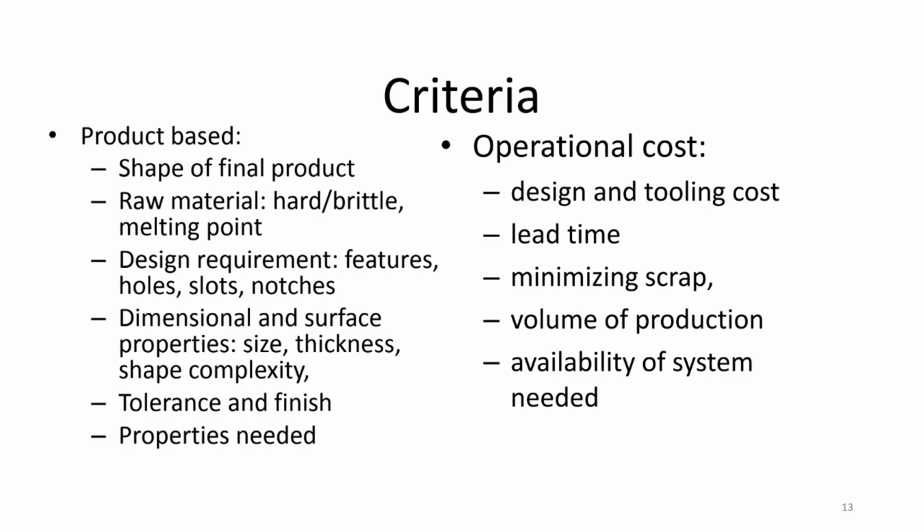For example, in case of machining, you get very good surface finish compared to sand casting. If you require a product with very good fatigue resistance, you require very good surface finish, so you require a manufacturing process which doesn't leave any keyholes or porosity on the surface.